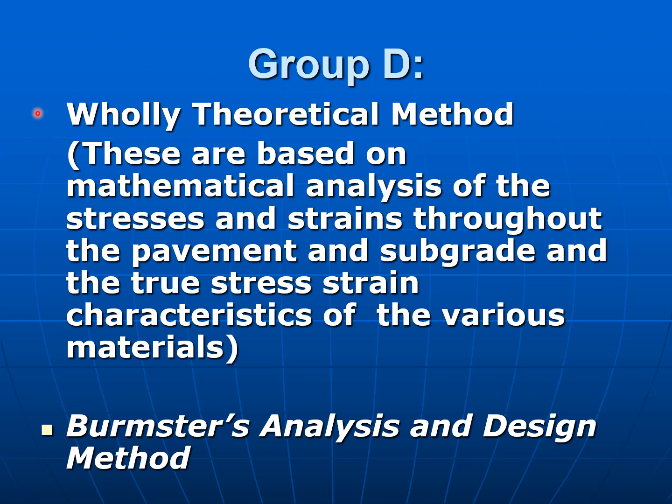Group D. Wholly theoretical method. These are based on mathematical analysis of the stresses and strains throughout the pavement and subgrade and the true stress-strain characteristics of the various materials. This is the most advanced method of designing of pavement. Here we have Burmister's analysis and design method under Group D.